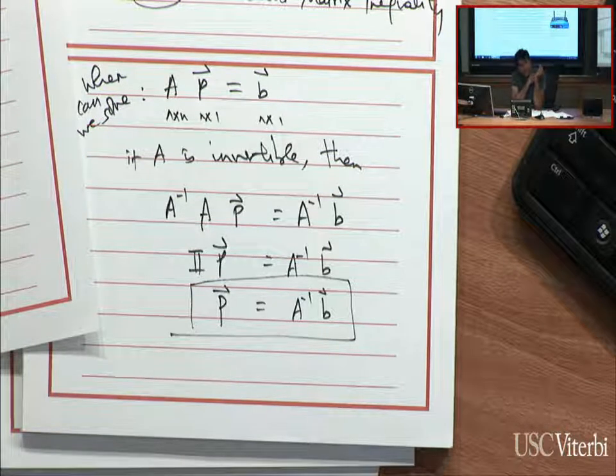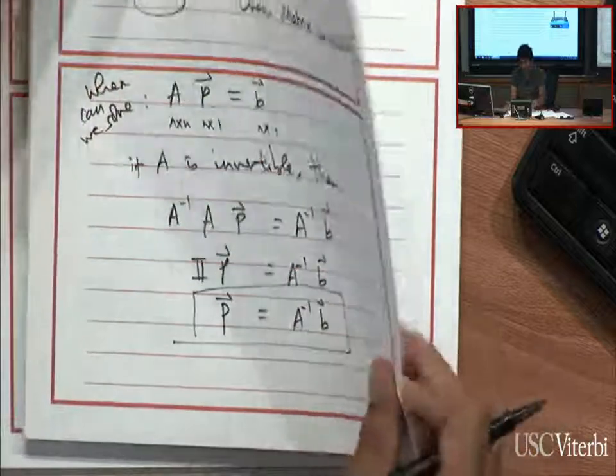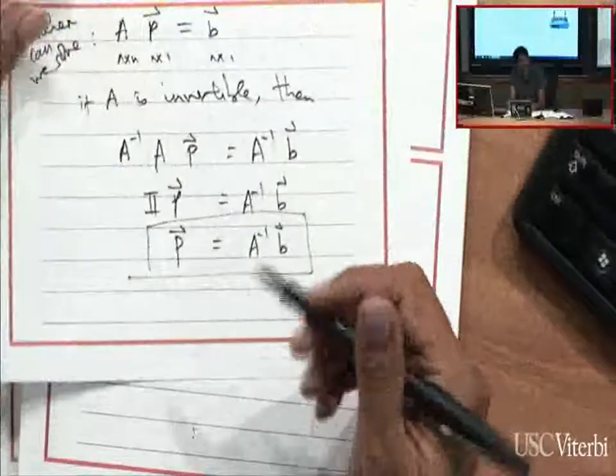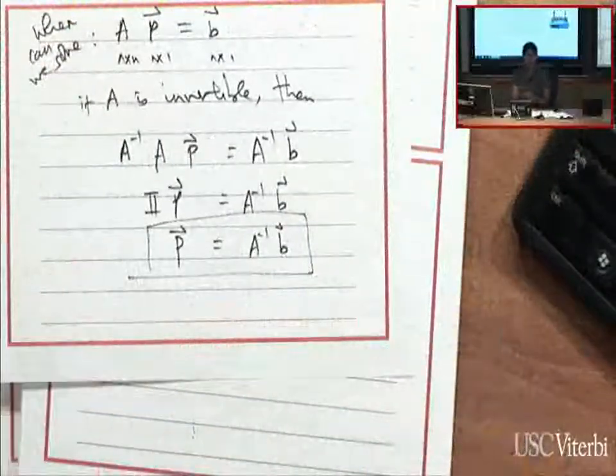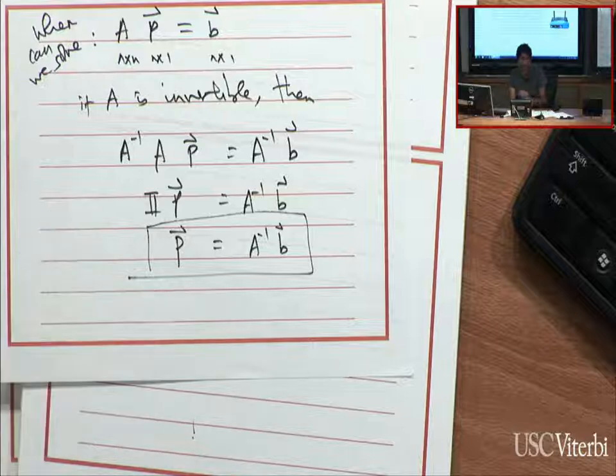And in the two-user case, we found there are conditions under which you have a solution. It turns out that was exactly the invertibility of a 2-by-2 matrix. So in that case, the problem was simpler, and we could work it out. But in general, if you write this A matrix, you know all the gain terms. You can write them as a matrix. If that matrix has an inverse, then there is a power control solution where all of the nodes can be allocated power such that they all just meet the threshold. And in fact, there are also solutions where they exceed that threshold. But you need this condition of invertibility of the A matrix.